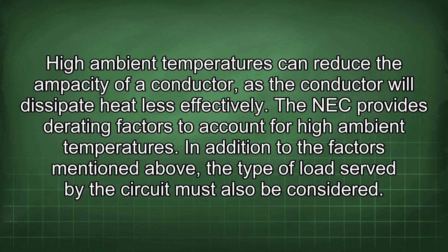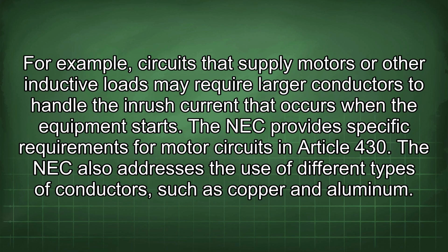In addition to the factors mentioned above, the type of load served by the circuit must also be considered. For example, circuits that supply motors or other inductive loads may require larger conductors to handle the inrush current that occurs when the equipment starts. The NEC provides specific requirements for motor circuits in Article 430.